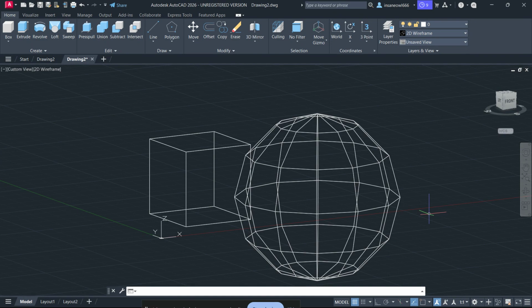Before we start fixing it, it helps to understand why this error happens. One common reason is near-coincident geometry. That means two objects are almost touching perfectly, but not quite. So AutoCAD gets stuck in a tiny mathematical gray area. Another cause is non-manifold topology, where the result of the operation would create an impossible solid, like two bodies sharing a zero-thickness edge. A third reason is self-intersection, where one of the solids is already damaged or corrupt and has internal faces folding into itself. Once you know the cause, the fix becomes much easier to narrow down.